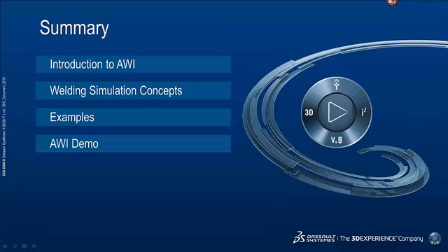For example, sometimes you make approximations on the energy input. So you take the bead volume and then apply a constant volume flux to the entire bead. It may give you different results compared to implementing the Goldak model directly, but if you're only interested in distortion or other aspects, there are many different methods of simulating this, and that's why we give you the framework so that you can implement your own heat source model.